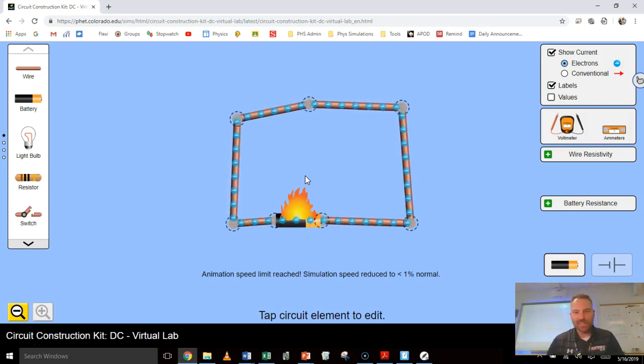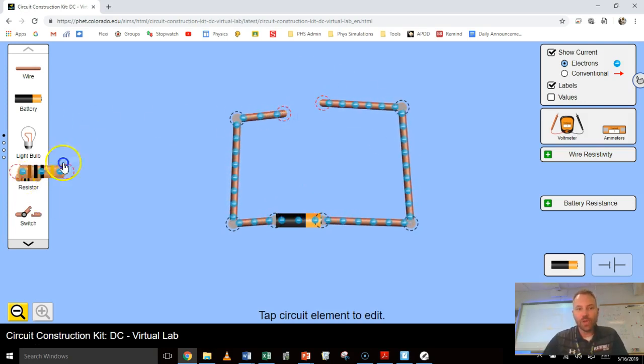A short circuit, it's short one of the three things. You're supposed to have a conductive pathway, a voltage source, and a load. If you don't have that load, you're short one of the things and it creates smoke, fire, maybe you've seen sparks. But when electrons flow, it creates heat. So you need to have some sort of load in there.